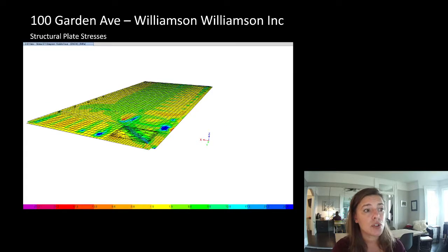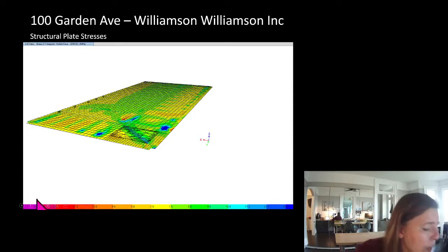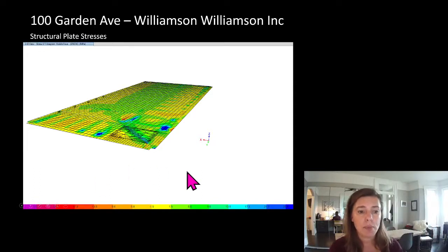Here is a stress analysis of the plate steel. And what's our maximum value here? Looks like we're at about 25 MPa. You guys remember, steel can go up to 350 MPa. Actually, this was stainless steel, so it could go up to 212 MPa. No, this one wasn't. This one was structural steel. That was the other canopy. So this could go up to 350 MPa.